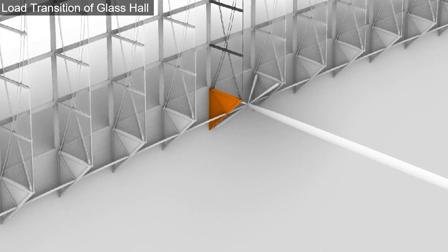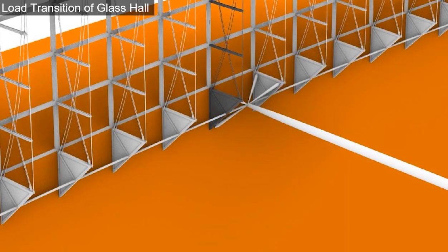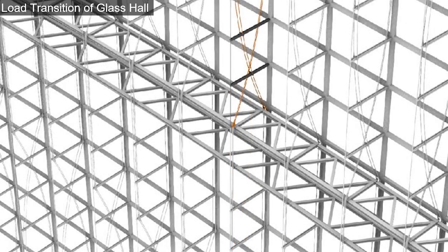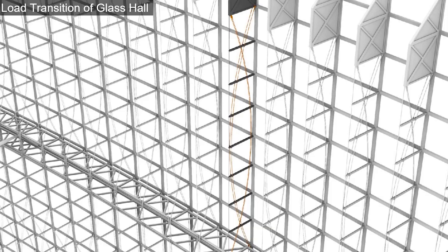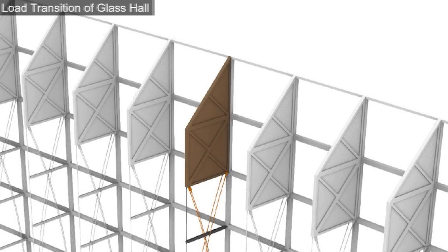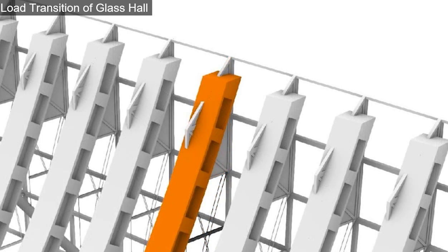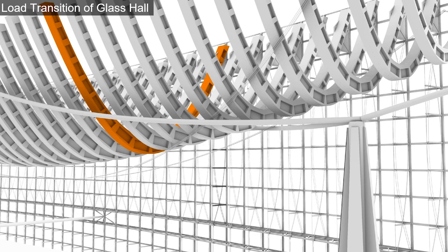The load transferred to the bottom first goes into the triangular plate, which is then directed to the foundation through the conference hall core on the east side, and through the first floor concrete wall on the west side. The load transferred through the top steel plate moves up to the roof structure and is supported by two main pillars, or large columns.